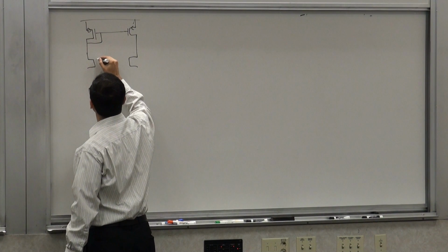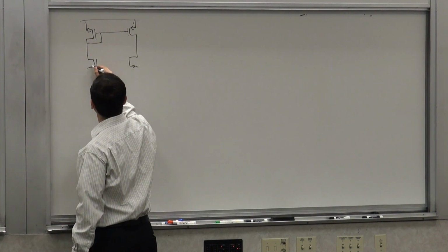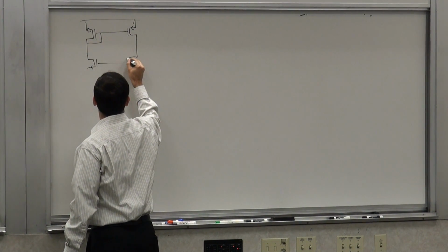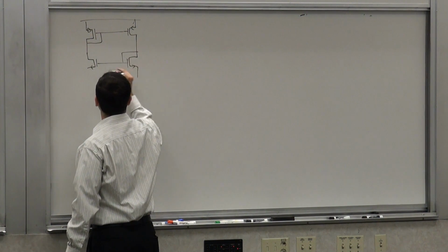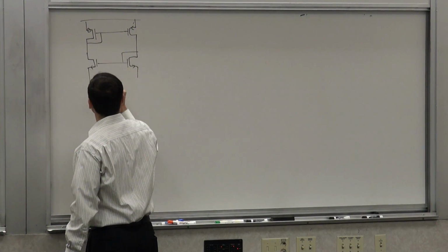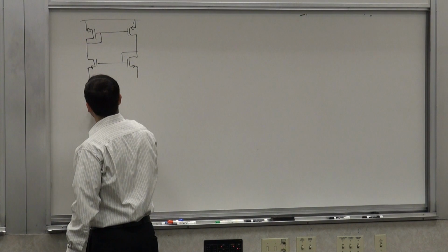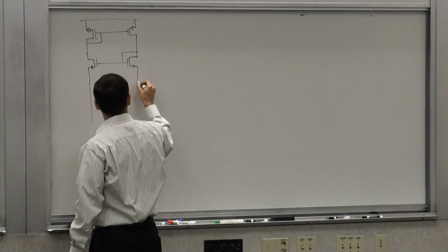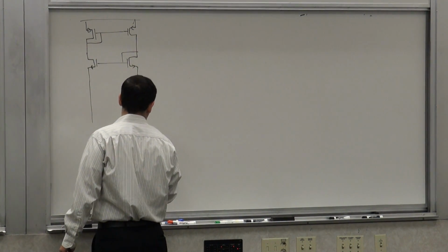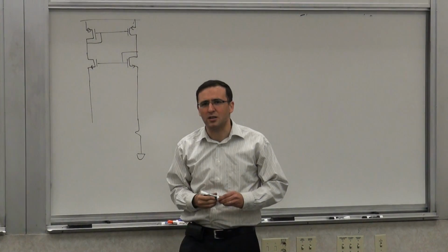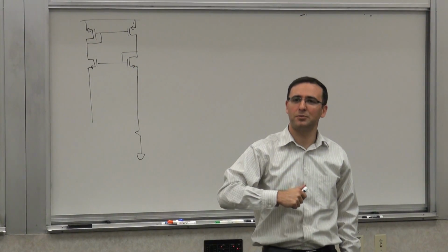The only key to it is that they can't be diodes connected on the same side. The isolator and the mirror should be diodes connected on the opposite side. Okay, so I'm going to make a VBE here. So I need some sort of a diode or diode connected device. But I'm in a MOS process. Let's say I'm in a pure CMOS process.